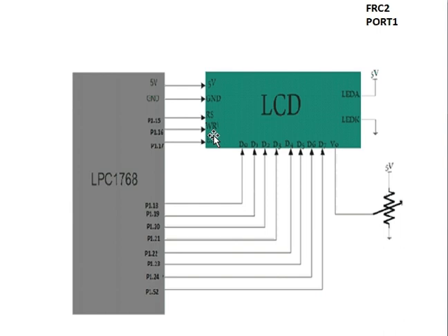And also we have selected WR pin, that is port 1 16th bit, this should be made 0 because we are writing something, and port 1 15th pin, this should be made as 0 because register select, if it's triggered as 0, it is saying that you're passing commands. If this is made 1, port 1 15th bit, then it means that you are passing data.